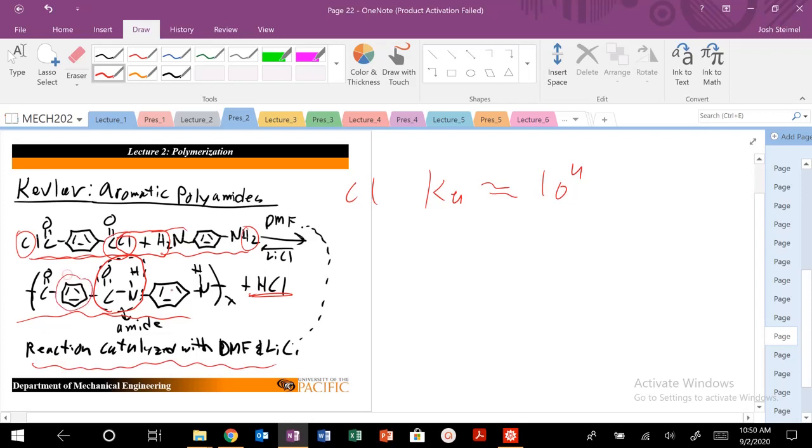These aromatic rings along the backbone are really, really bulky. So sometimes, and actually oftentimes when you're producing Kevlar, you need to catalyze this reaction because we need some of the unique behavior that comes from Kevlar. So Kevlar is able to absorb the impact of a bullet. One of the reasons is along this backbone you have these aromatic rings, lots of double bonds and carbons. So this is a really, really rigid backbone here. And we also have these amide linkages all around that allow us to do intermolecular hydrogen bonding. So that leads to the mechanical properties of Kevlar as well.